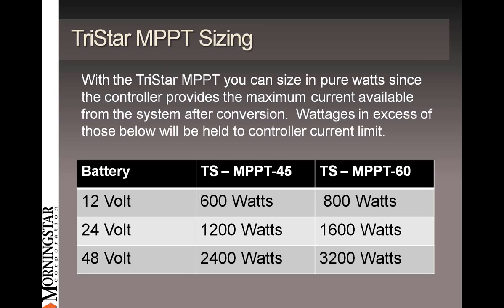But most importantly, you should know if you exceed the wattage rating of the controller, it won't damage it. It's just going to only operate at 60 amps maximum output. Okay, so if you put 3500 watts instead of 3200 on, that's fine.